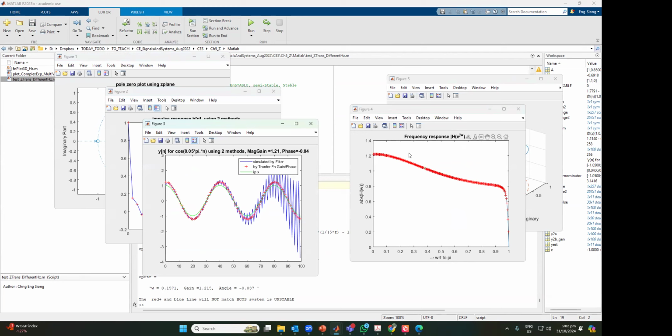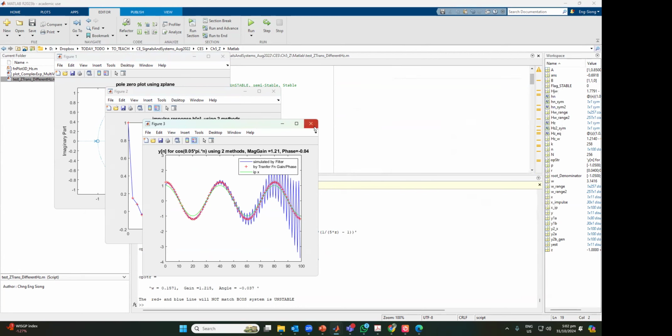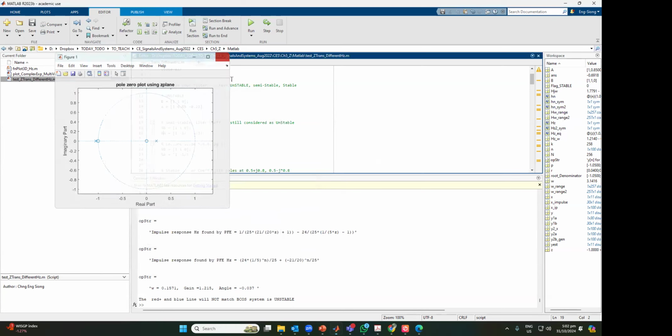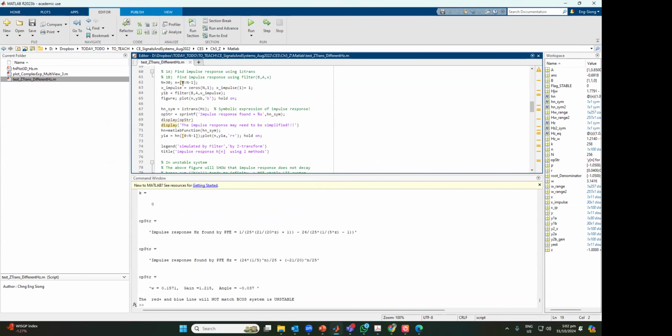But the frequency response and all this you can still calculate. So don't believe the things when it is unstable. Then H(e^jω) doesn't make sense at all. It's just math, but it's wrong. I'm going to plot a longer impulse response now so that you can see that it's going to be unstable. So I now have 130 samples.